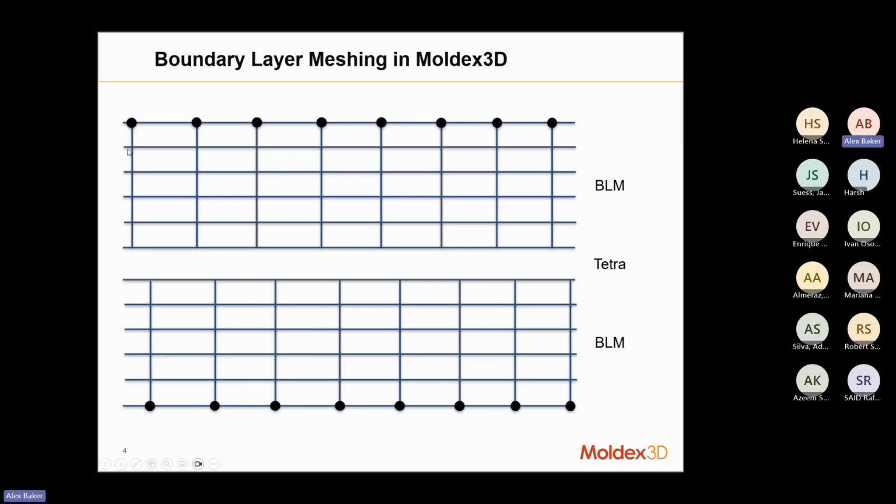Actually, in an ideal world, we would be able to extrude these nodes all the way from the top surface to the bottom surface. But in order to do that, we would have to have the exact same node array between the top surface and the bottom surface, which just really isn't possible for any reasonable geometry. Maybe for something like a plaque or a dog bone or some sort of regular shaped object, that would be possible. But for any sort of real geometry, you really won't have the same contour across the top surface as you do on the bottom surface of your geometry.